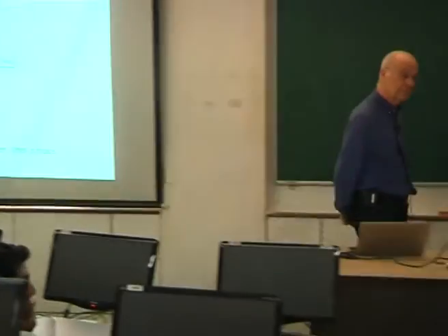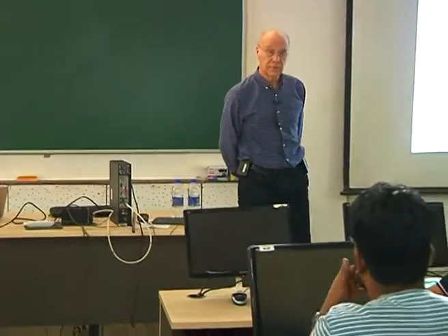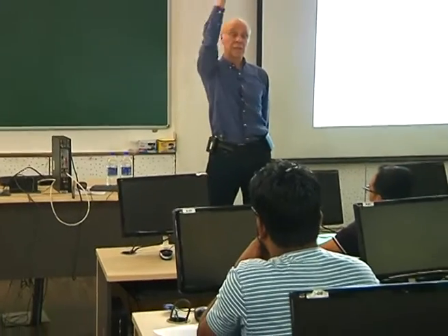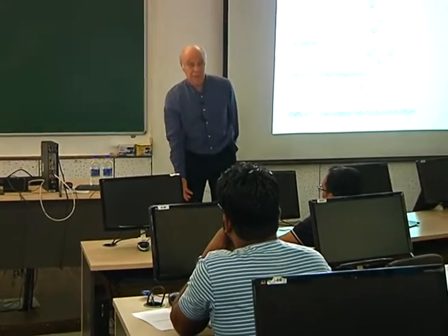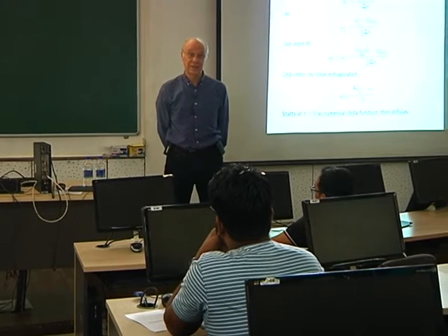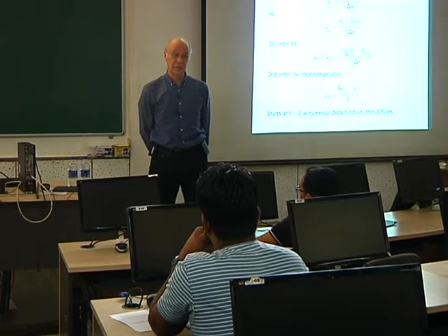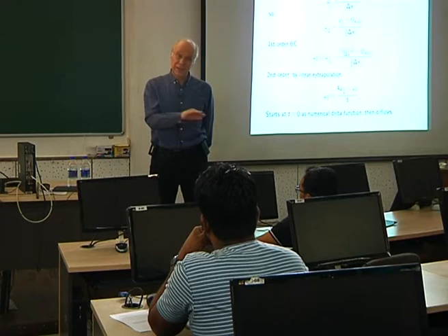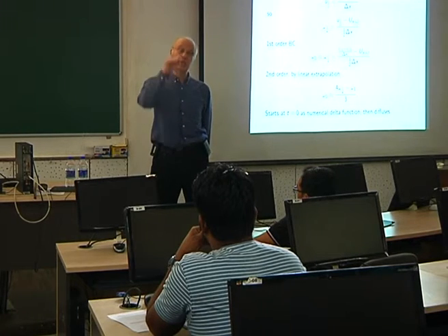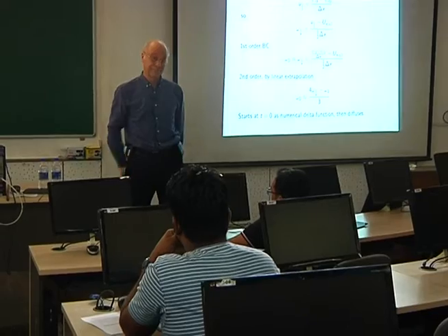That was we are getting the stream function above the wall. Yep, you can do a Taylor series expansion in y, and then identify the terms. The second derivative in y is the stream function, because along the boundary there's no x derivatives, but once you start going up, there are x, y derivatives you have to start worrying about.